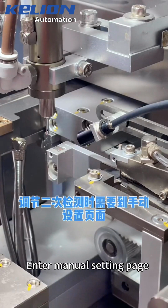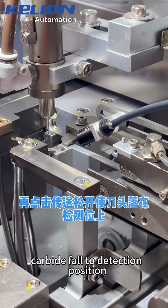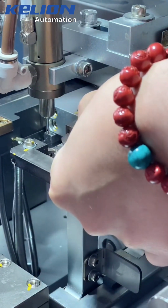Enter the manual setting page to adjust the second detection. Click transmit clamp, retaining needle up, detection position. Then click transmit loosening, and the carbide tip falls to the detection position. Then adjust the lens of the second detection. That is the same as the first detection.